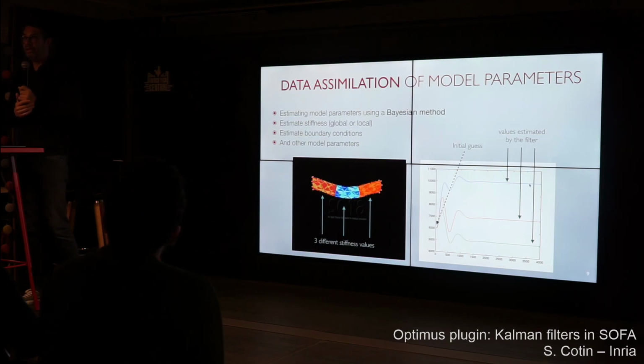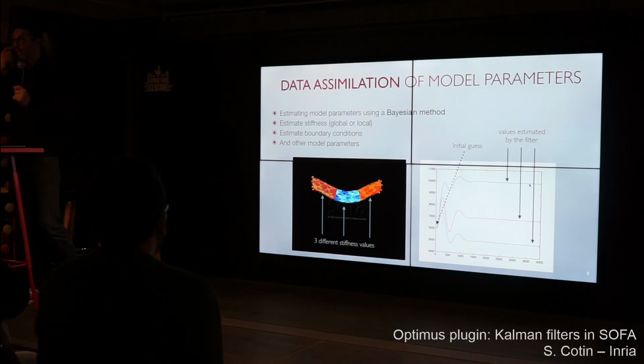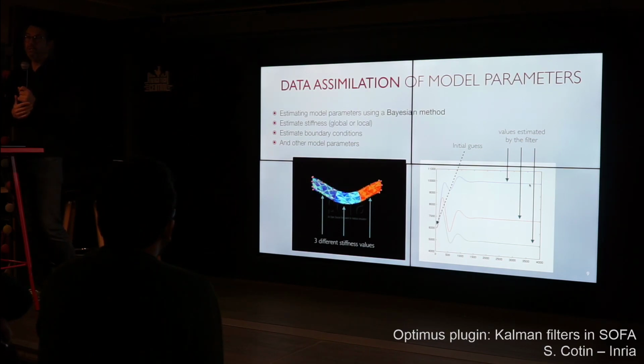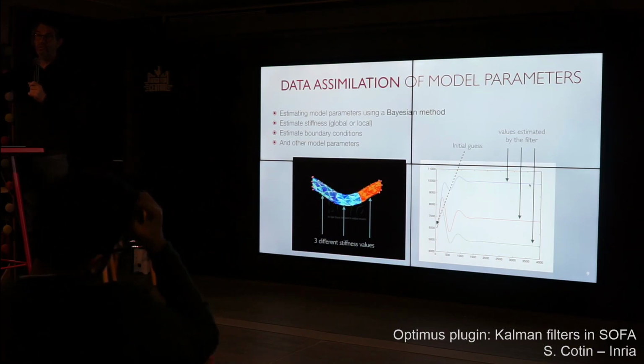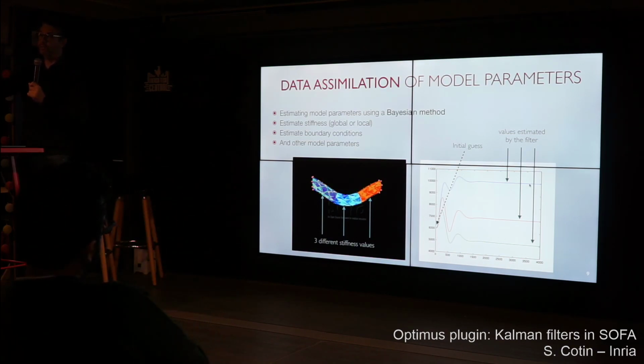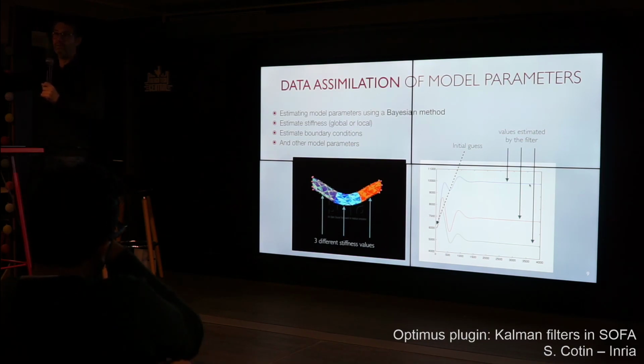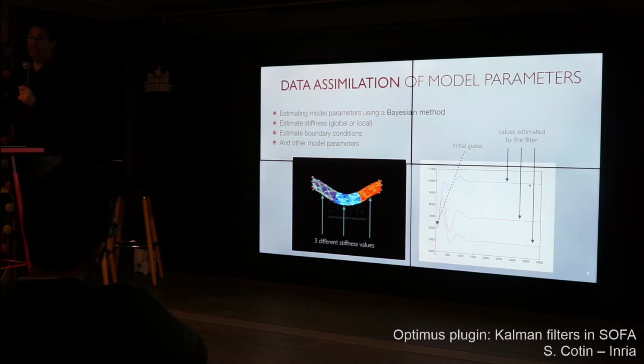But we think it's useful, for instance, to tune model parameters to mimic real-world objects. I don't have pictures of that, but we took a catheter that we simply placed against a vertical surface and measured its shape over time. With a few observations of that, you can estimate the Young's modulus of the catheter and feed that into the model for some other simulation.